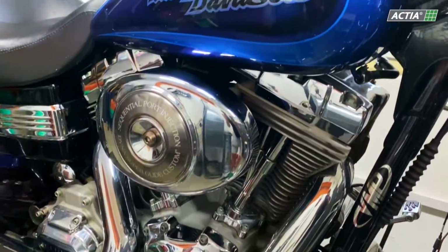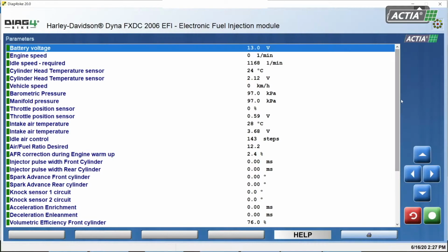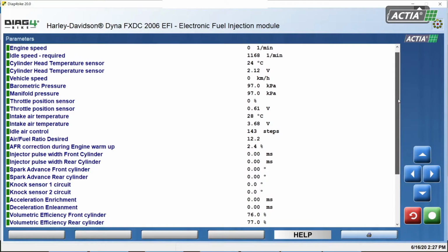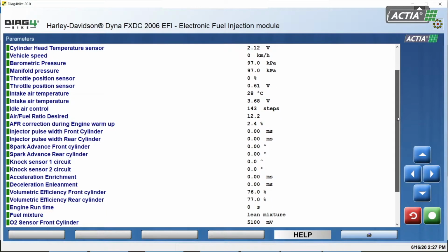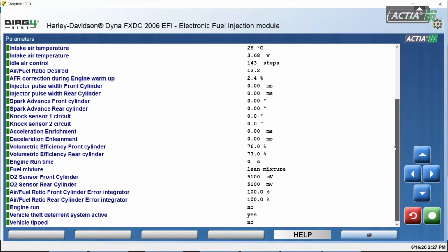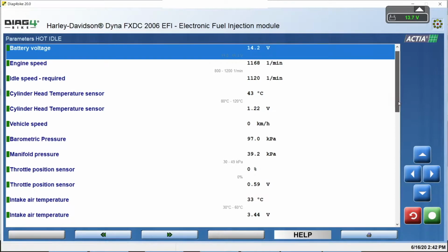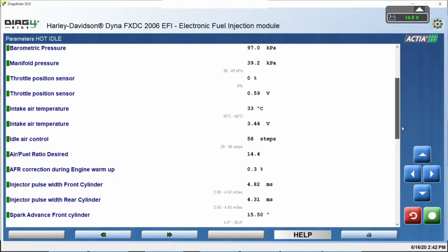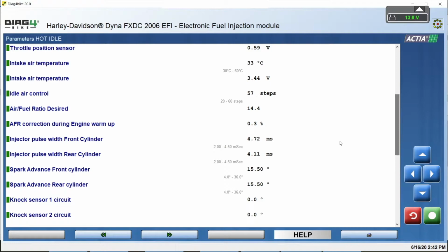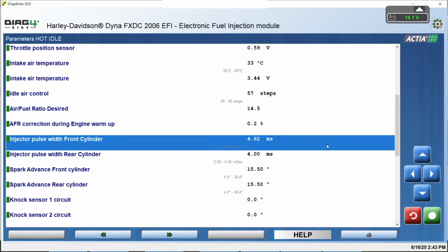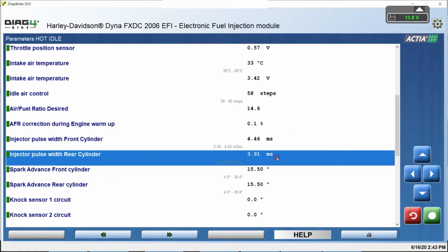In case of problems, it is best to verify the accessibility of these inputs and outputs with a measuring instrument, such as a voltmeter or oscilloscope. Parameter measurement helps reveal many faults that would not be discovered by reading the fault memory. The operator's first step should be checking the veracity of information. This analysis can help reveal partial faults on temperature and pressure sensors, for instance.